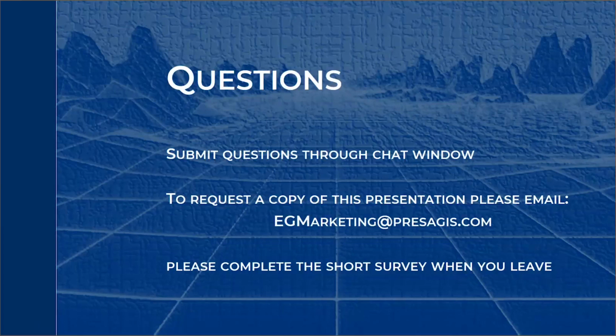However, if I start using it as a pilot and I'm trying to scan around the sky and look at stuff, the classical head-up display rules start applying, because you don't do a head-up display typically at less than 60 hertz. So you're looking at 15 milliseconds there for things to be updated on the screen, because you start getting disorientated because it is in your line of sight, and it's meant to correlate with the terrain and the actual scene around us.